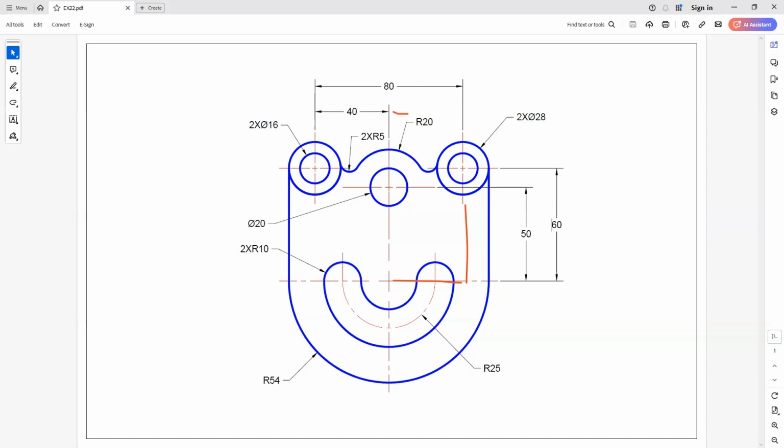So therefore this distance here should be 40, right? So that tells me that it's going 40 in the X direction. And then the number for the Y direction is simply a direct number. It's located here. Alright, so I can simply type in the coordinates and say create me a circle that is 40, 60, and then type in the diameter of that.